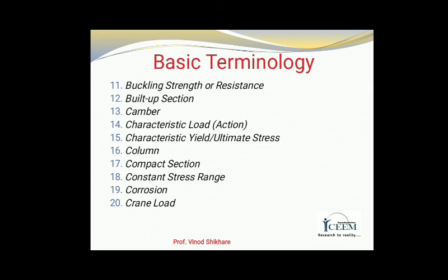Camber is the intentional introduction of pre-curving, usually upwards, in a system member or any portion of a member with respect to its chord. Frequently, camber is introduced to compensate for deflection at a specific level of loads.